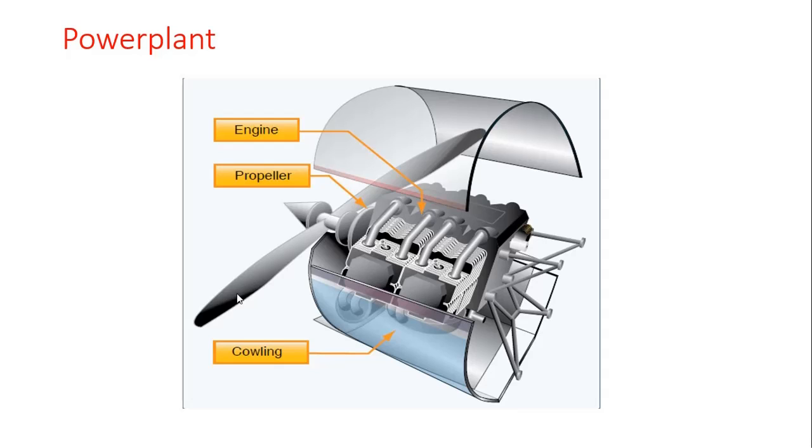The amount of lift being produced by the propeller is directly related to the angle of attack, which is the angle at which the relative wind meets the blade. The angle of attack continuously changes during the flight depending upon the direction of the aircraft. The pitch is defined as the distance a propeller would travel in one revolution if it were turning in a solid. These two factors combine to allow a measurement of the propeller's efficiency.